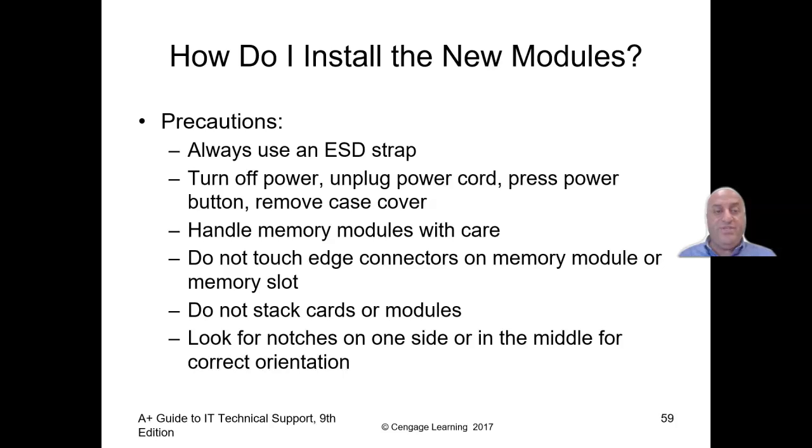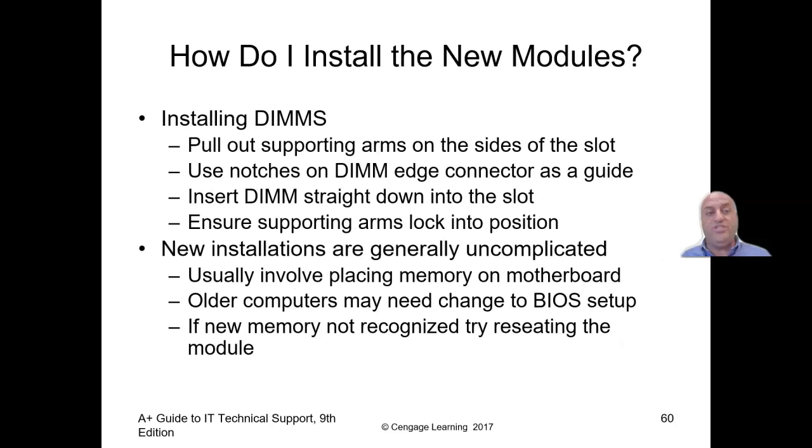Precautions here: always use an ESD strap. Turn off the power, unplug the power cord, press the power button to drain the power, then remove the case. Handle memory modules with care. Don't touch the edge connectors on memory modules or memory slots. Don't stack cards or modules. Lock notches on one side or the middle for the correct orientation.